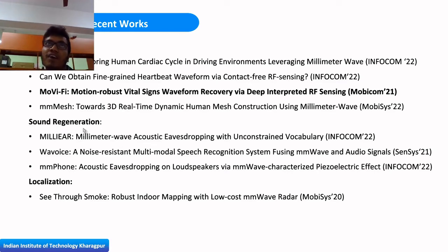So you have a certain sound source, maybe a speaker or a human vocal fold. Okay, the human vocal fold or the speaker has certain vibrations to generate the sound, right? The task of this millimeter wave FMCW radar is to capture these vibrations. Once these vibrations are captured, from that vibration spectrum, vibration waveform, how can we generate the actual acoustic signal? That's the challenge they have addressed in this sound regeneration domain. In Infocom 22, we have two papers where they have addressed the same challenge. One is where they have used a speaker, and based on the speaker's vibration, they try to generate the actual acoustic signal.